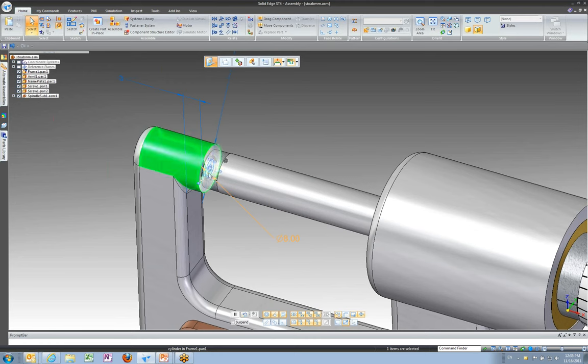Again, if you get something like this where your steering wheel is in the wrong direction, just use these little control nodes to snap it 90 degrees from where it was. So now my steering wheel is pointing straight up. I'm going to click that arrow to start the move. And let's take a look and see what happens.